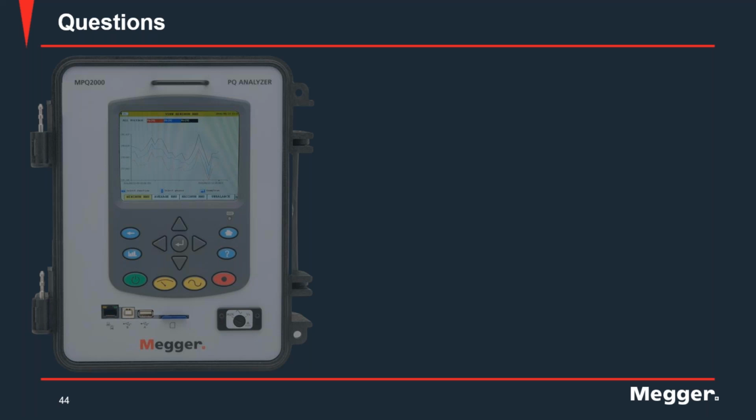So that would indicate that this problem can either be from a faulty rectifier somewhere else in the system, but you also say with the loads off, you're not seeing it. So this really seems to indicate that this is a harmonic issue. That's most likely the cause of it. Even in here, it's mentioned that if you are using a filter, it does help somewhat. So you may want to try putting a line reactor in there to see if you can block some of the harmonics.